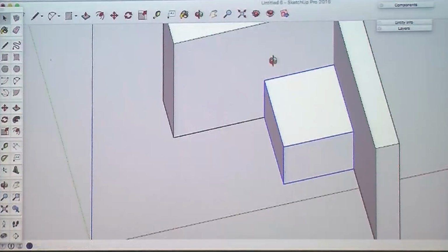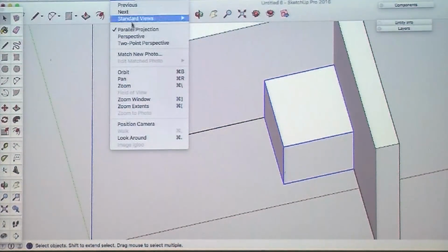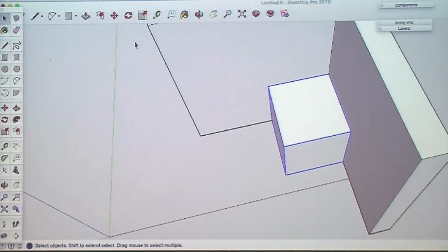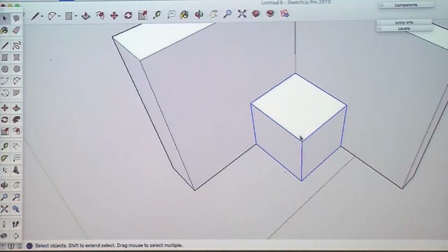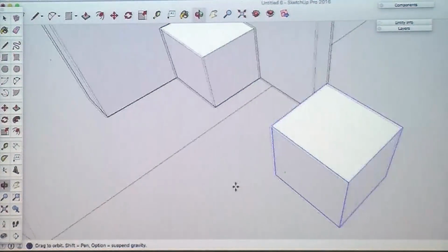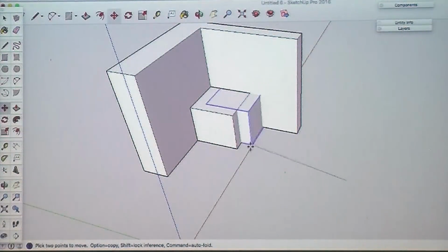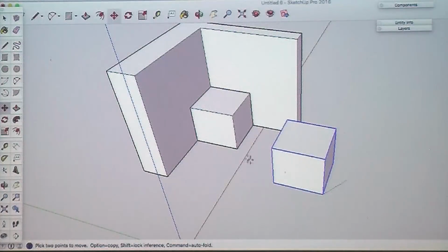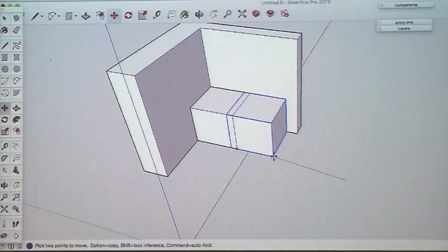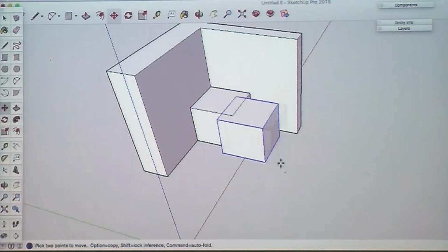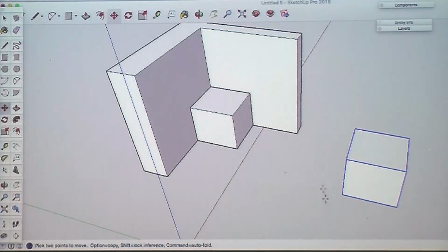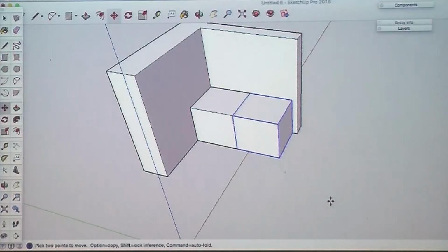For the subsequent ones, it's like when you're installing them in the field. You get that first one perfect, perfectly leveled, attached really well to the wall. Then when you bring in another cabinet from 3D Warehouse, sometimes the base point isn't right. It'll come in attached to your mouse pointer like this, so you can't perfectly put it where it belongs. So you just set it down somewhere else, click your move tool, click on that base point, and snap it in like that, and you can keep building off your cabinets like that.